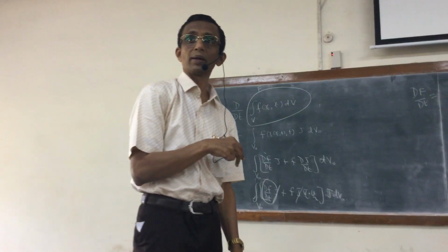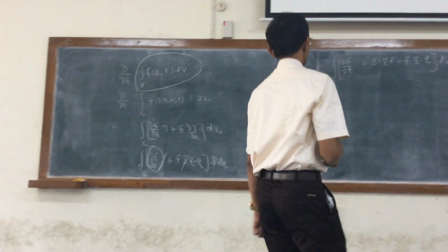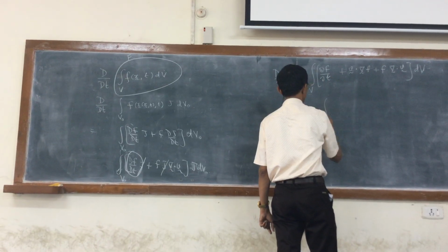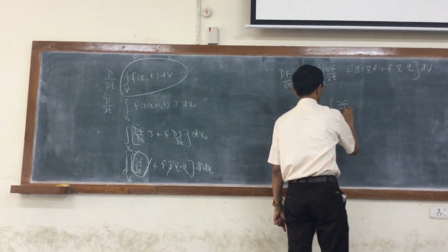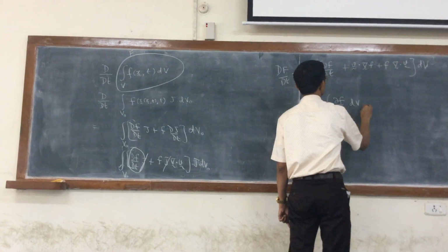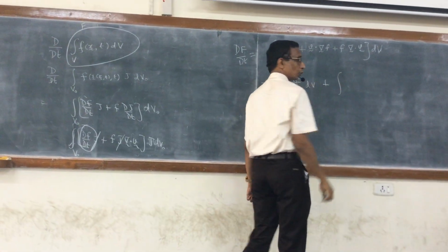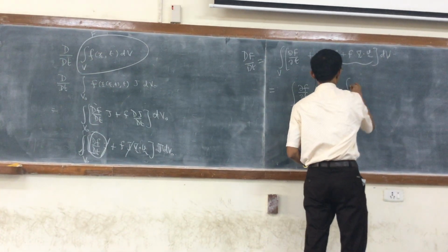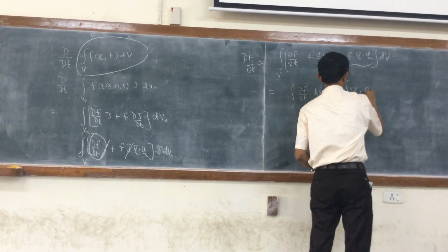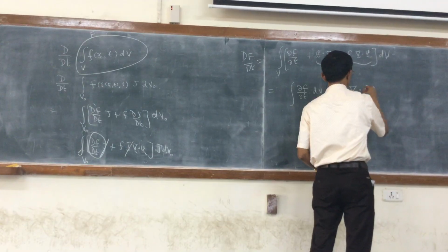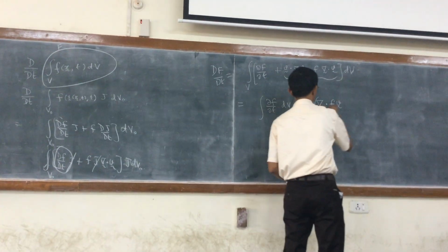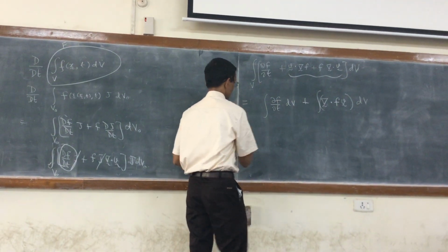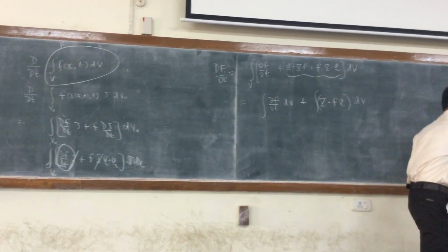So, back to the integral over the spatial domain. It can now be written as df by dt dV plus, without proof, I showed that this group of quantities can be written as the divergence of the scalar f times v. Quite easy to prove that.